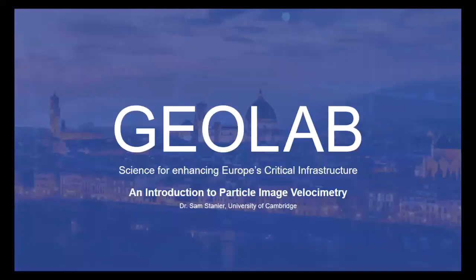Your other question that you asked me about stereophotogrammetry. Yes, we've used it a little bit. Mainly what we've been using it for is to image the surface of triaxial samples. So we're using multiple cameras, which we know the location of. And so what we do then is we use PIV to find coincident locations in the two output images from each of those cameras. And then we can use epipolar geometry in order to identify the full three-dimensional position of those points on that sample surface. And that's working quite nicely. We're just about to publish a couple of papers with colleagues at UWA on that from work that's been ongoing the last couple of years.